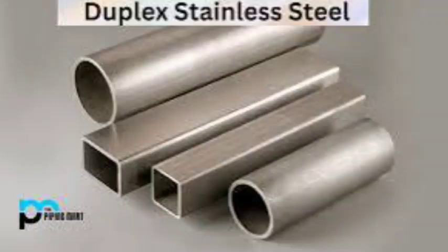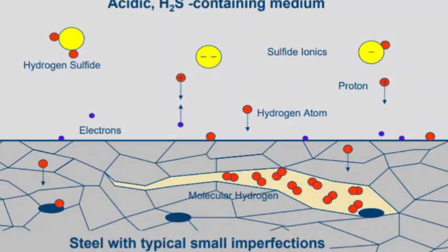First in CRA is SS316L. Then it is evaluated for DSS, then for 825, then for 6 moly and SDSS, then for 625. So this is the only criteria which decides the material selection: temperature, pH2S, chloride and pH. Based on the operating parameters, we select the CRA.